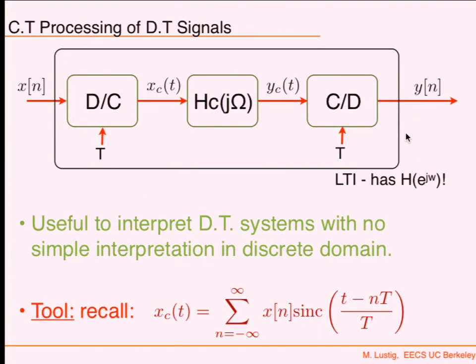If one has aliasing, let's say this is slower than this one, then we're going to have a problem. If they're both fast enough but different, does that change it? I don't think it's going to be LTI anymore. It will be like upsampling or downsampling, effectively. It'll be linear if they're fast enough and there's no aliasing, but they're not going to be LTI.